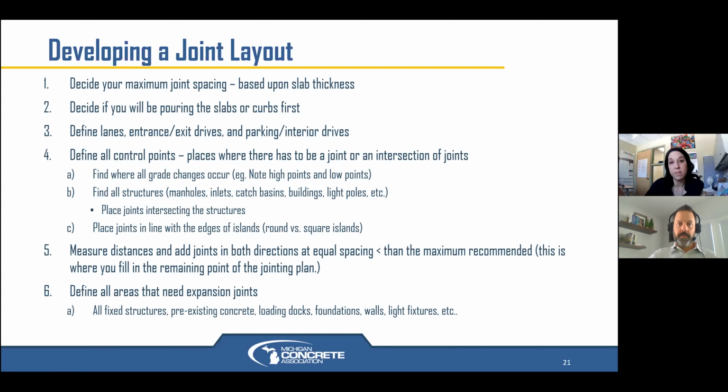Yeah, we just want to make sure that whatever your foam is makes the full depth so that your concrete doesn't bond underneath that foam, because sometimes we see that in the field where they order a 6-inch, but really one of the pieces of concrete is an 8-inch or a 10-inch, and you might have an issue with it bonding underneath that foam.